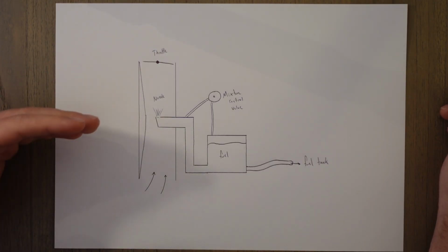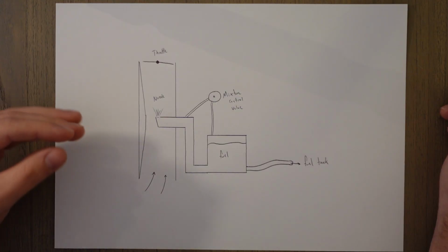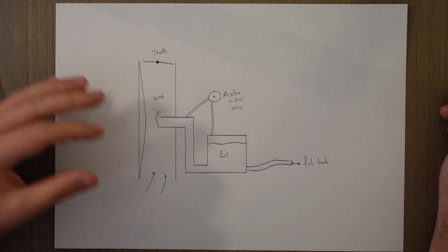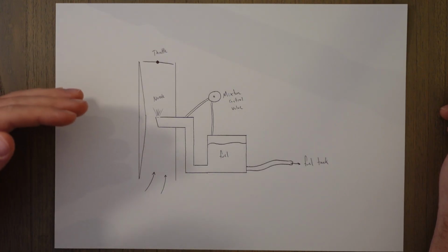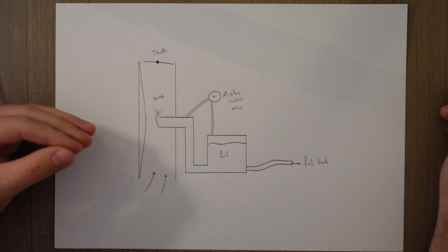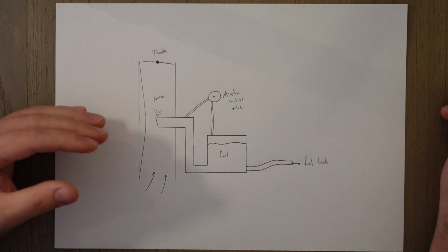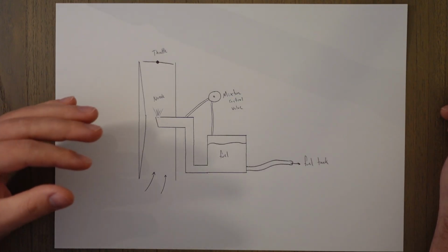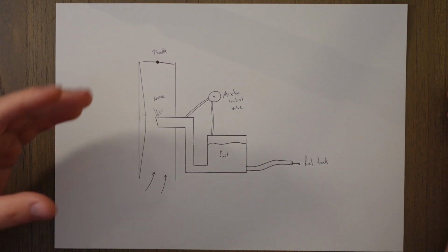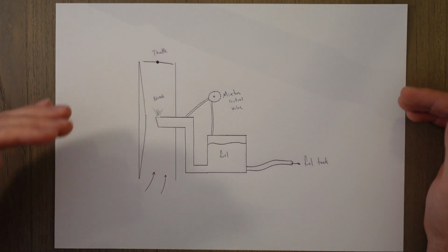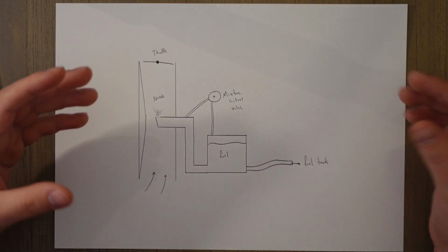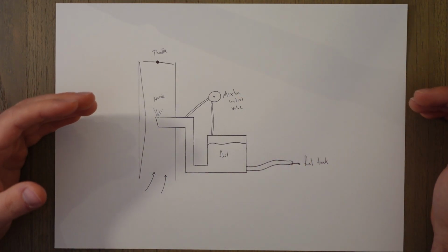The fuel to air mix that gets combusted in the cylinders is also very important. You need to get the correct ratios. If the fuel to air mixture gets too hot, it can detonate instead of combust. This is when the fuel ignites and burns too quickly, which releases all of the energy suddenly and can overstress the engine. We therefore need to control the combustion so it's consistent and doesn't risk this explosive detonation.